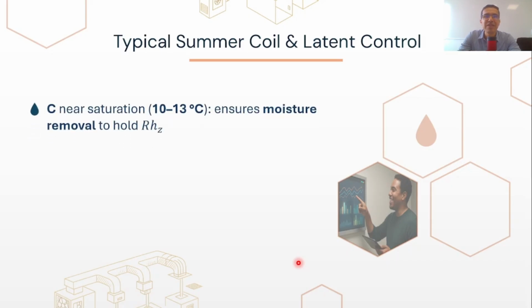The air exits the coil, at state C, as I mentioned, near saturation, typically between 10 and 13 degrees.